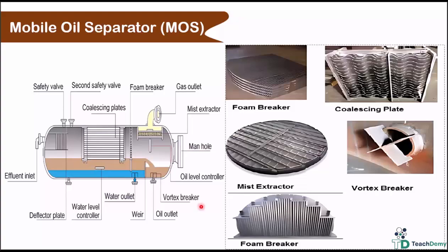and pressure resistant. A three-phase separator is an industrial device designed to simultaneously separate oil, water, and gas, taking into account incoming flow conditions, internal pressure, and corrosive environments, including the presence of acidic gases such as hydrogen sulfide. This separation ensures the prevention of vortex formation, foam breaking, and proper operation of downstream pumps and equipment.